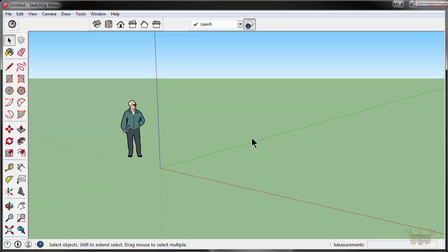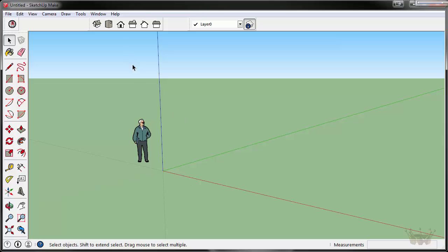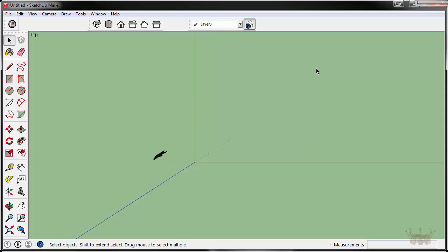For this video, we use all of the tools, techniques, grouping, and components to create a simple house. After moving Frank slowly off of the midpoint, let's press our top-down view from the view bar so we can see directly over our drawing. Using our pencil tool from the midpoint, we're going to come up for a value of 25 feet.